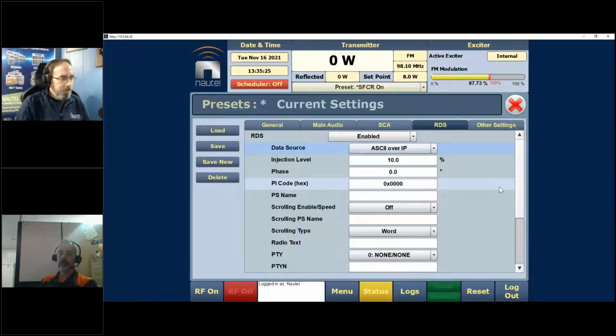Yeah, same. The ARM processor is only so big. So if you're using stuff like SNMP, RDS over IP, and you're doing constant get commands, or constant sending of data over RDS, it can cause the ARM to stop responding.